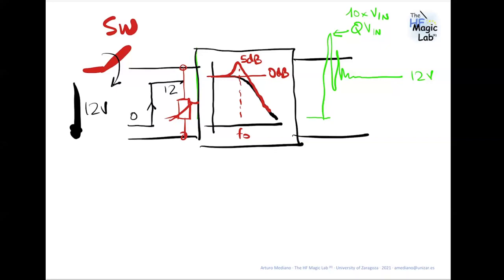Great, thank you. Could we do the same DM and CM separation with 2 RF voltage probes instead of 2 LISNs, larger equipment? No, because you need to offer to the product some specific impedance, and this is what we get with the line impedance stabilization networks. So I think the answer is no. Okay.